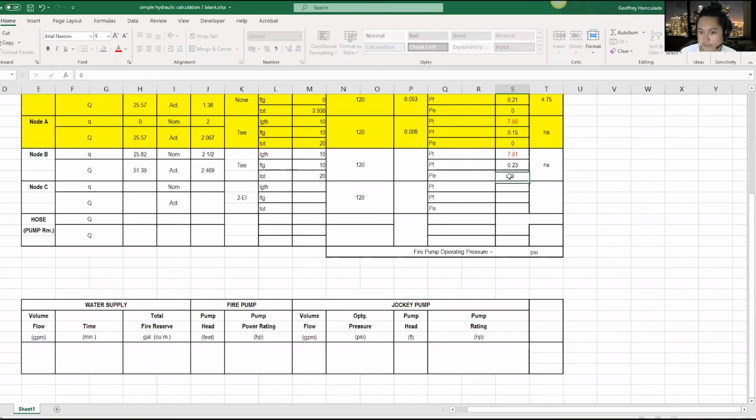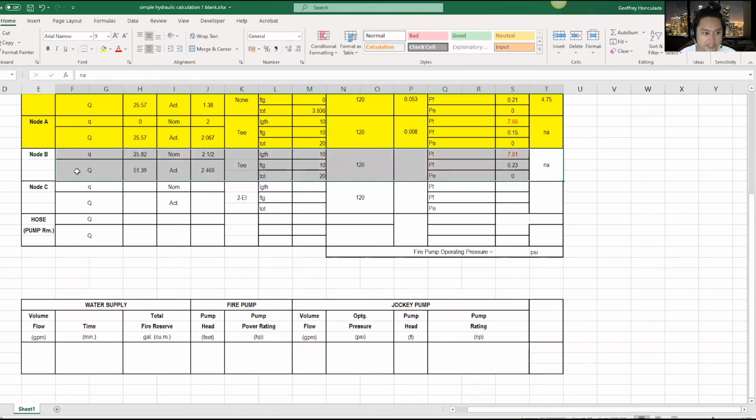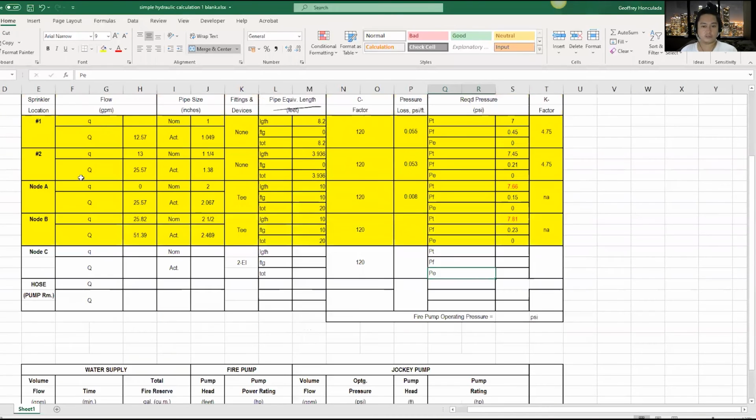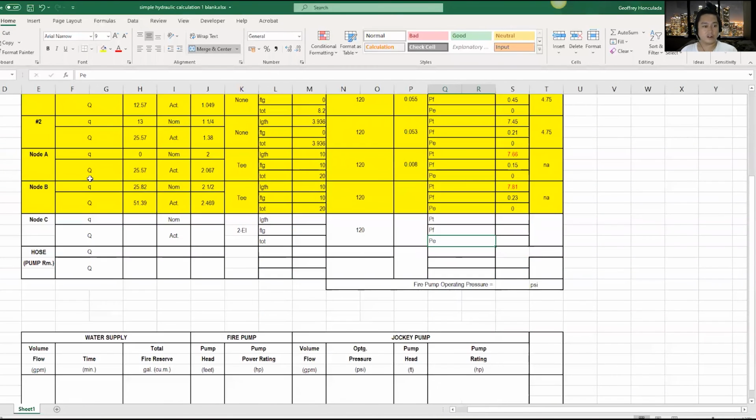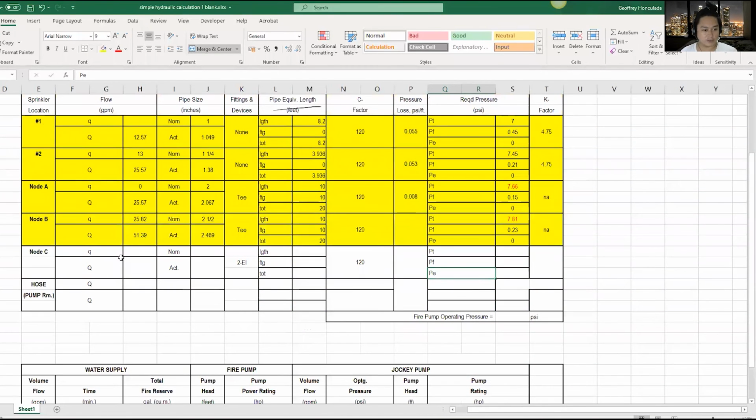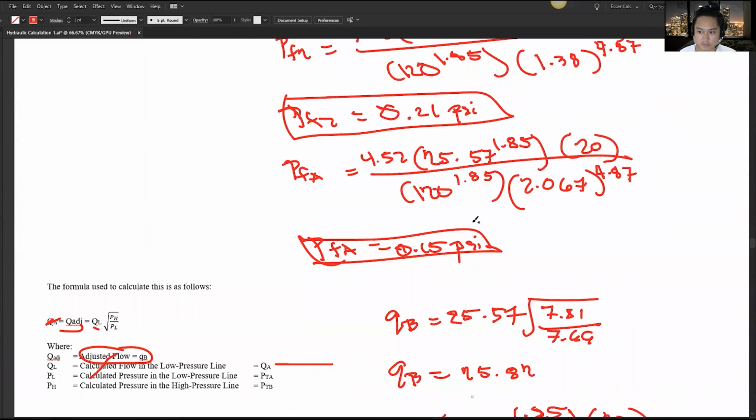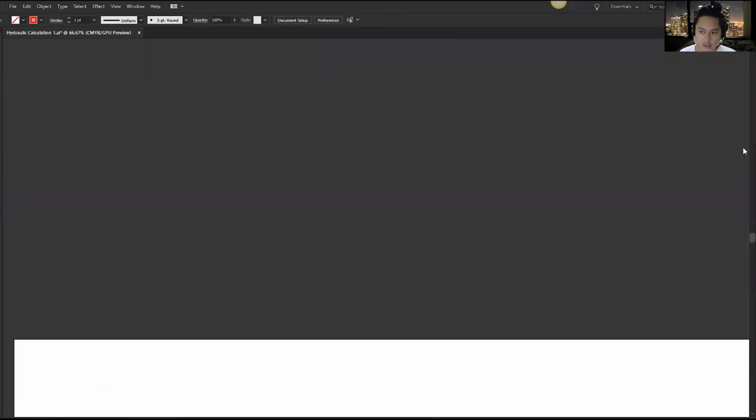And we'll input that in our table, which is 0.23, and we've got zero elevation, so we don't need any pressure requirement. Node B is filled out. We're almost done. We're already at node C. Now, solving for a small q is the same as the flow adjustments, because if you've noticed, it's just a symmetric design. It's from node A to node B to node C.